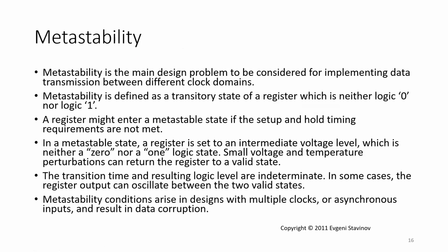If clock domain crossing is not well designed, I may get into a metastability. Metastability means that upon the rising edge, I have data that has just changed from 0 to 1.